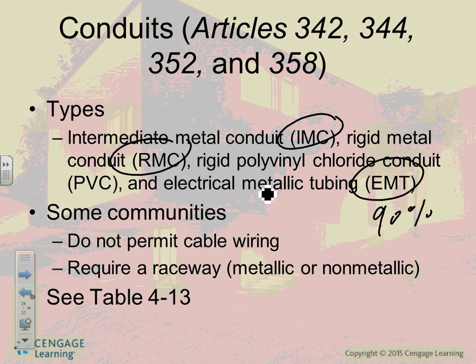The same, it looks exactly the same, I don't know if you guys can tell from there. These are also threaded. You can't thread this one, but rigid also comes threaded, so it's stronger. Instead of sliding the connector in here, you have it threaded here. Where would you use this one? This is for severe physical applications. Manufacturing floor, forklifts running around, service coming out of the ground right next to a parking lot. Chad is drunk, ran right into it.